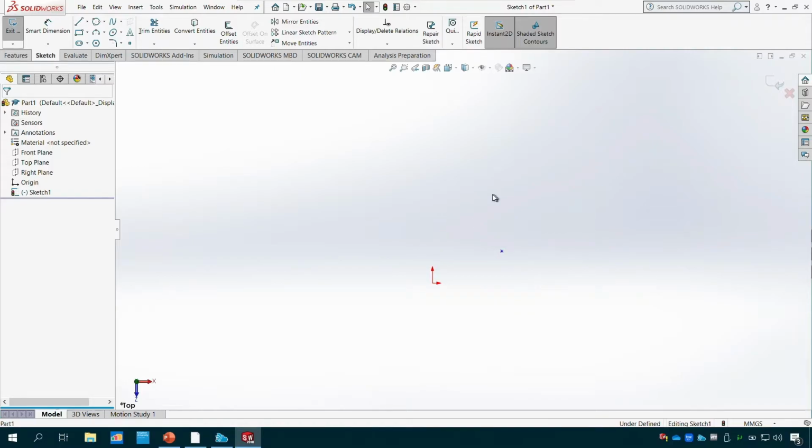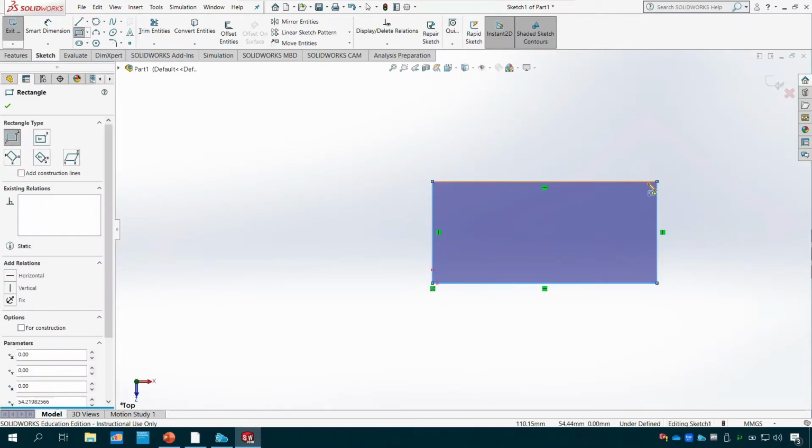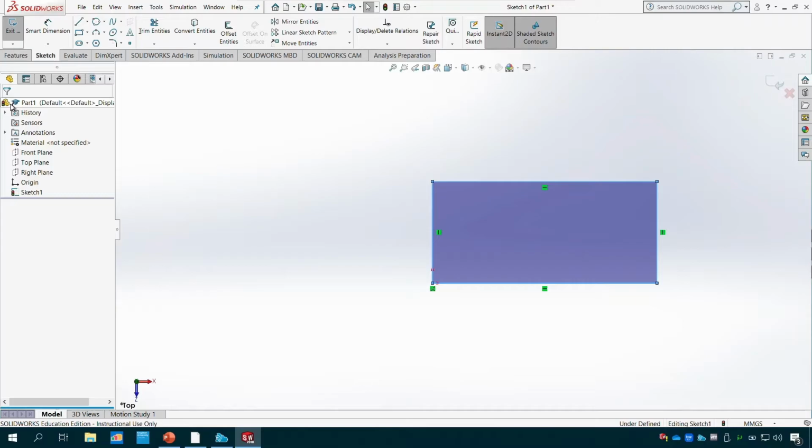So let me get rid of that point as well, and let me talk about, for instance, the fillets and chamfer. If you look at the kind of product you're watching me on, whether it's a phone, a tablet, a laptop, a computer, using the monitor, you will see that there are some sort of curvatures on the corners. So for instance, let's assume that they are a form of rectangle. You will see on the corner there is some sort of curvature, which we call the fillets. There are plenty of reasons we have fillets, but one of the common reasons is to make it, of course, much more appealing, but again, it would be easier to manufacture.